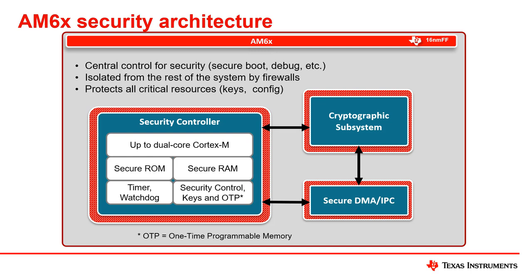As we mentioned earlier, this is kind of an island set apart within the chip, in order to do security operations. For example, you don't want a Linux process running on your Cortex-A processors to be able to come in and read your one-time programmable keys or hashes that your security is all based upon.